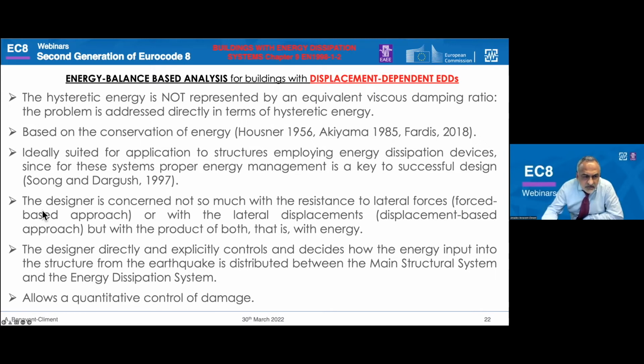In this method, the designer is not concerned so much with the resistance to lateral forces or with the lateral displacements, but with the product of both, that is, with energy. And not with monotonic energy, but with cyclic energy. The designer directly and explicitly controls and decides how the energy input into the structure from the earthquake is distributed between the main structural system and the energy dissipation system. And this method, as you will see, allows a quantitative control of the damage on both the main structure and the dampers.